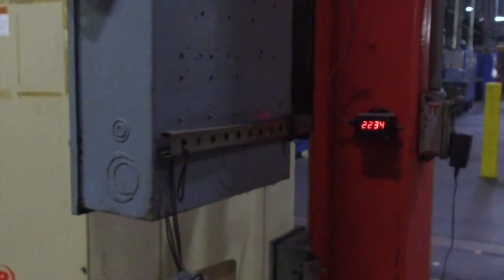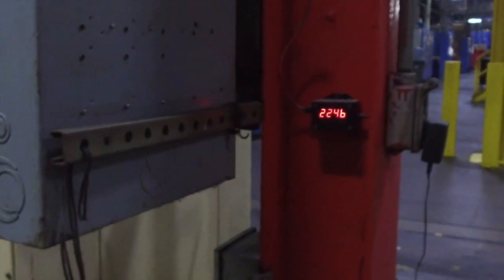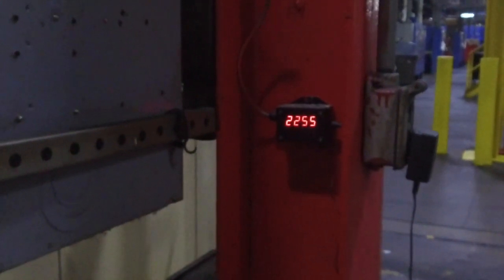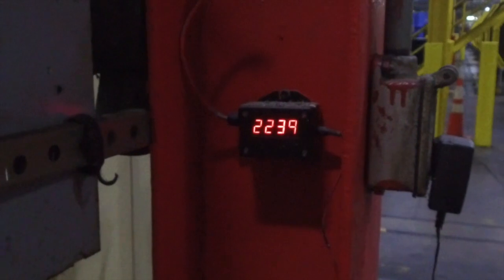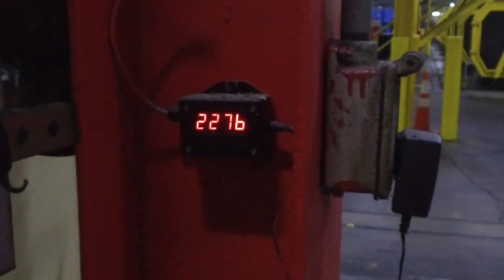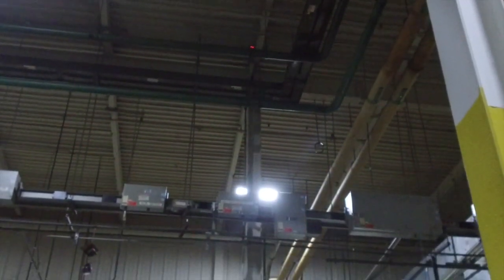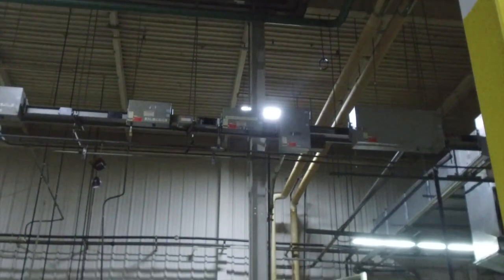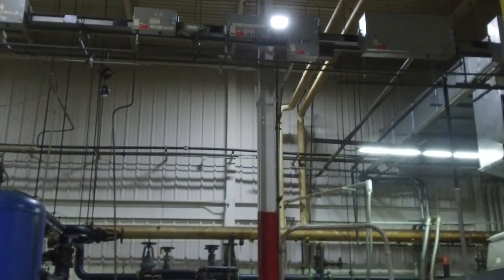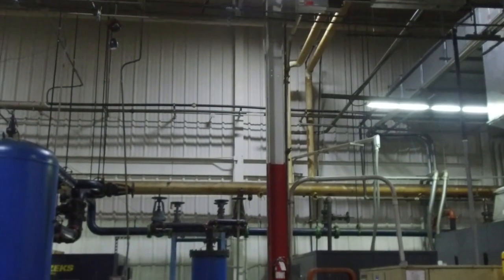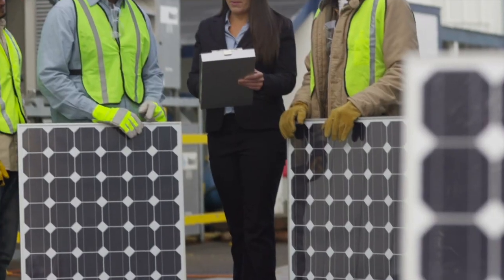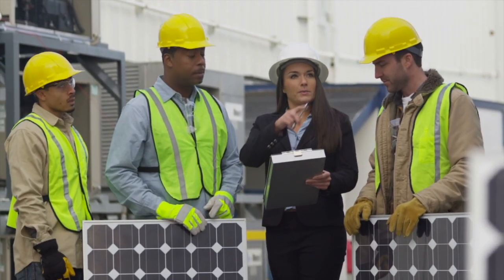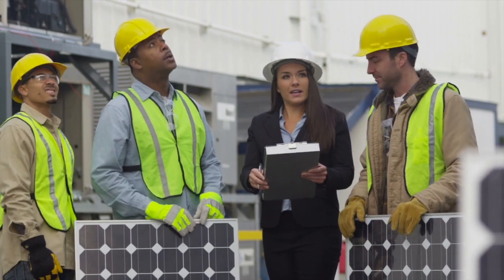Another way to determine compressed air usage would be to set up flow meters at various points throughout the plant. There you could physically measure how much air is being used. This gives you great insight into the plant's actual compressed air usage over time. But this is not done as often as you might think. Flow meters cost money, and air use will change anytime you have even a small change to your process. The bottom line is, when a plant is designed, the size of the compressor is often guessed at by management. This leaves the possibility of a greatly oversized system, and is the reason that compressed air usage is one of the first things that a good energy manager is going to look at.